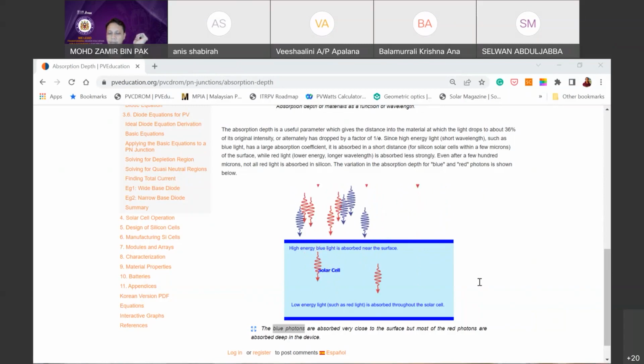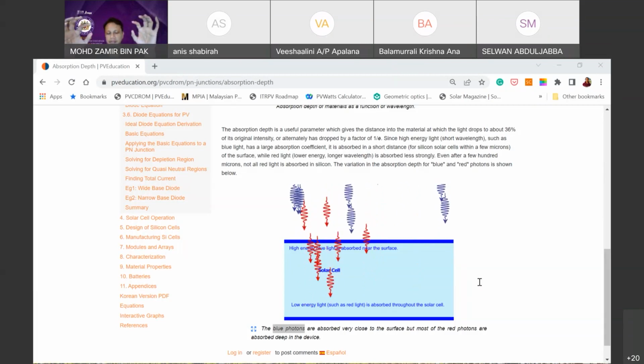My PhD last time was in light trapping schemes of photons in solar cells. That means I only need to use somewhere around 10 micron of crystalline silicon instead of 200 micron. But at the same time, I need to ensure that most of the photons are absorbed. So you need to stretch the capability of the crystalline silicon. You need to incorporate more optical strategies in order to trap the light, trap the photons. Meaning, the volume you have is just this much. So in principle you can only absorb this much. But how do you then absorb most with only this much thickness of crystalline silicon?